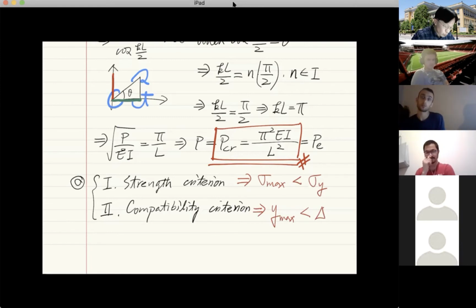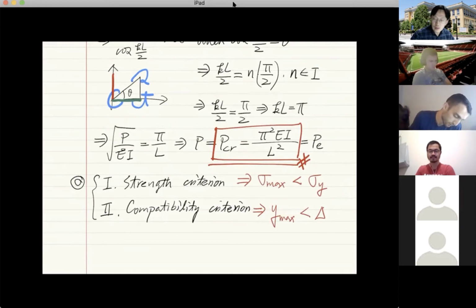So sometimes when we look at the maximum deflection, Y max, we want to know what the maximum Y max will be when we consider a beam column member. Because the difference between beam column members, as we established already, is not because of the critical load, but because of deflection. So we will use this buckling expression here to check the maximum deflection for beam columns.